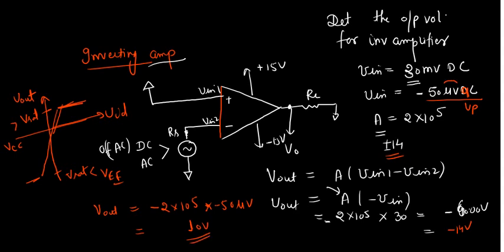Right? So what can you observe here? If your signal is very, very small, in the microvolt range, then you get amplification. It will not be clipped off. Got it? 10 volt peak comes under the plus minus 14, right? Plus 14. This 10 volt means what type of sinusoidal signal you will get? This type, right? 10 volt. And the input was in microvolts.